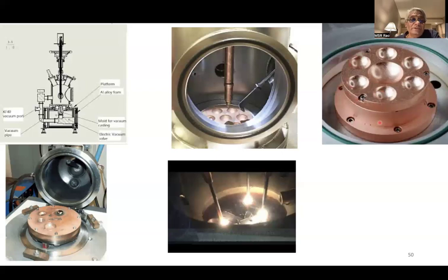Water is always circulated at about 20 degrees centigrade. So the surface is always cooled rapidly, always at 20 degrees centigrade. Whatever heat is generated during the process of the alloy formation is continuously taken away by circulating cold water. So that's a beautiful way of keeping the copper hearth intact. It won't melt and react with the alloy that you need to make there.